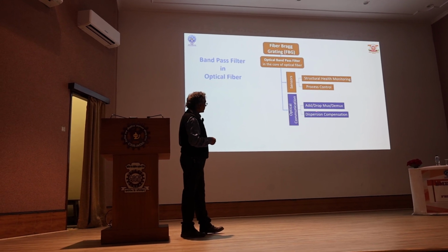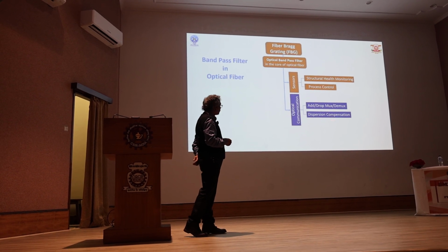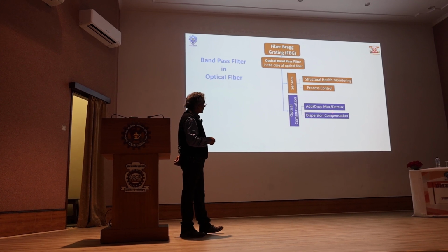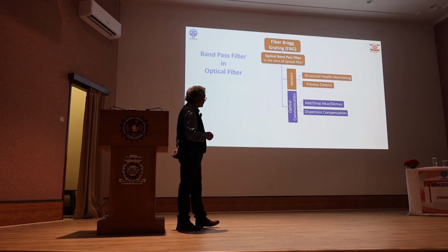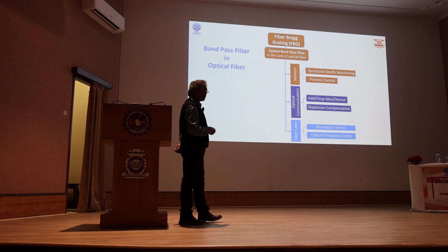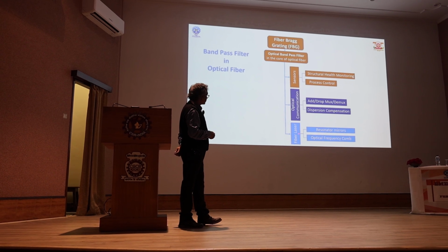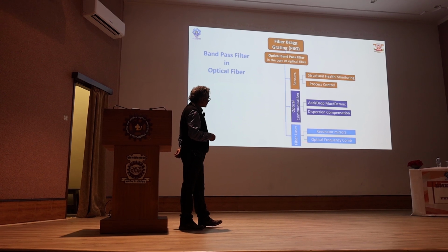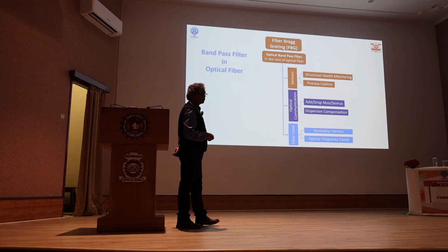In optical communication, it has several applications in a product form, where add-drop multiplexer and dispersion compensation are examples of two very important devices. And finally, developing fiber lasers, means when optical glass lasers are being transformed into the form of fiber optics, then developing this fiber optical laser, it has applications using the same filters for resonator mirrors and optical frequency comb generation.